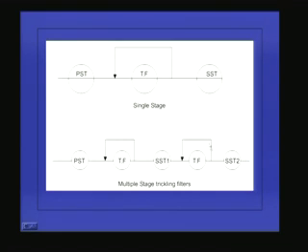And here also, instead of recirculating from here, we can recirculate from here also. But many studies have shown that whether we recirculate from here or after secondary sedimentation, there is not much change in the efficiency of the system. So we may as well recirculate from here so that we can reduce the volume of the secondary sedimentation tank.